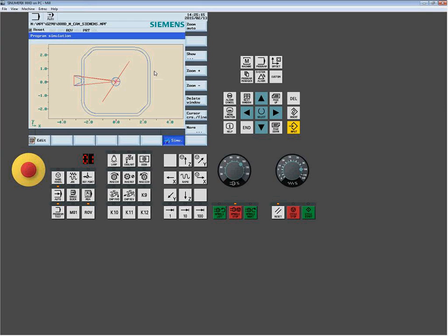So, what I wanted to start to show you here, and this is very common when dealing with a hosted program where you're compensating for the tool radius already. On this, so right now, I have offset tool 1 set up at a 0 cutter radius.